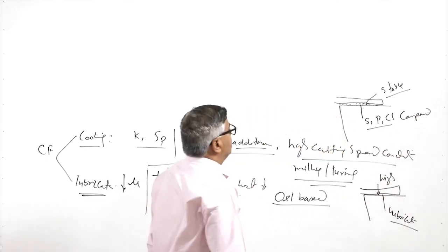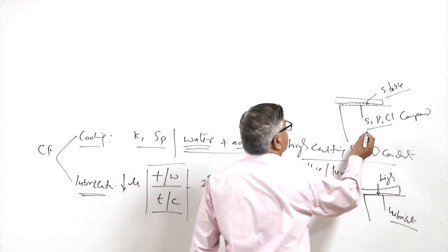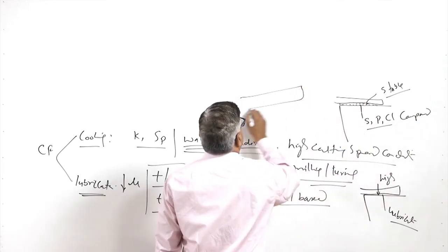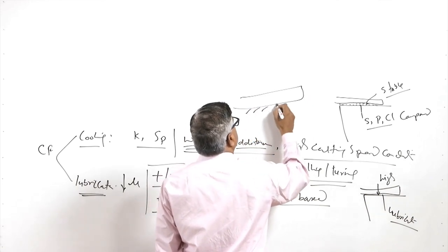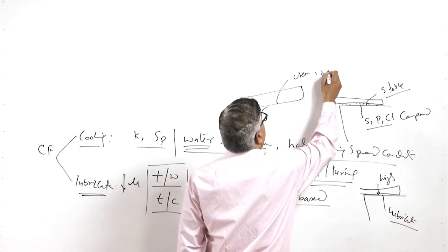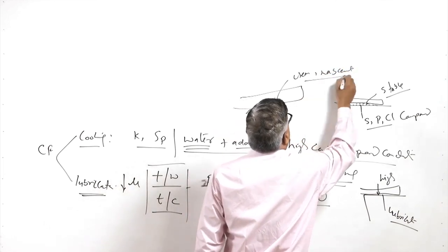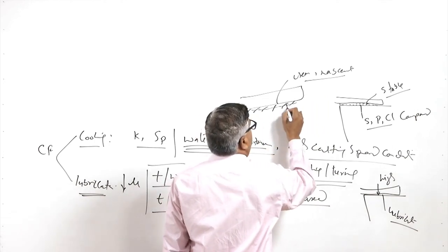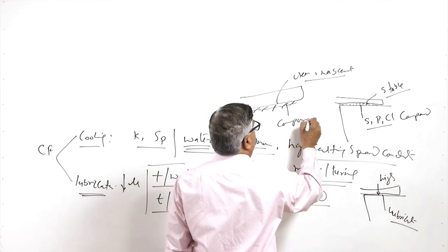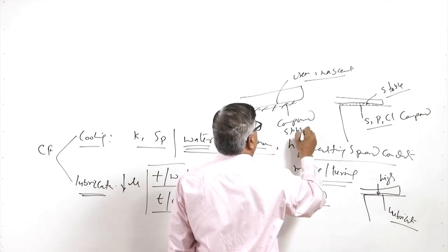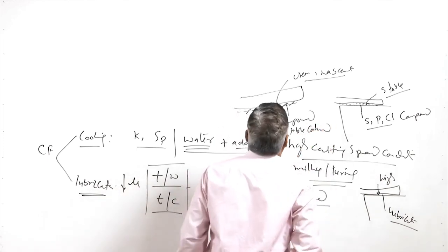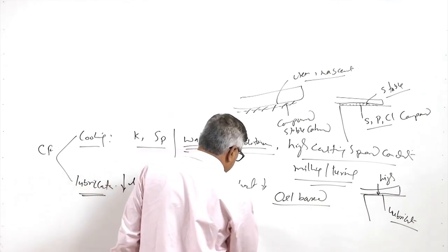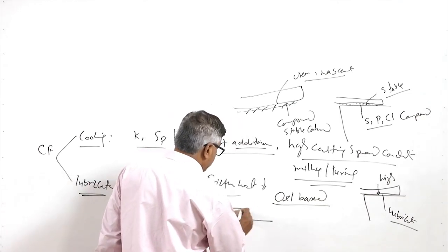So, these compounds basically interact with the machined surface as well as the chips, like the under surface of the chip, which is very clean, very nascent and fresh. So, these compounds actually interact with the fresh metal surface and form certain compounds which are more stable and coherent. When these compounds are formed, they can remain stable even under extreme pressure conditions.